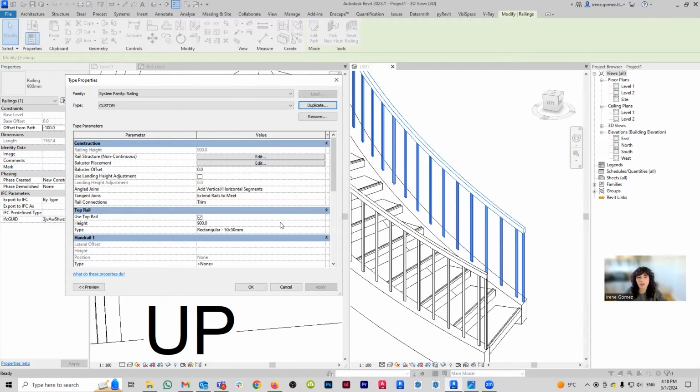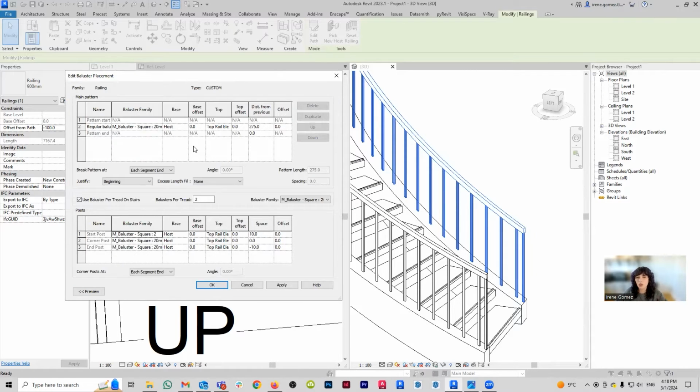The main issue here is that if we go to the instructions for my balusters, you're going to see that all of my balusters are instructed to connect to the top rail. So if my stair rail is made out of a single top rail and a bunch of balusters that go to that top rail, and I delete the top rail, the balusters have nowhere to go and the whole thing collapses. So this is just to warn you that you want to be careful a little bit because sometimes one of these changes can break things.